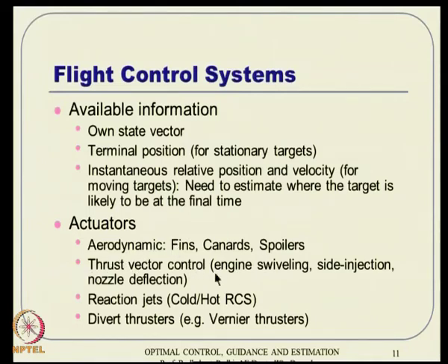Then there are thrust vector control, such as engine swiveling, side injection mechanism, and then nozzle deflection mechanism, things like that, by which the thrust vector is purposefully deflected away from the missile's own axis basically. Then you will get a lateral component of that, which will give you some sort of moment to turn actually.